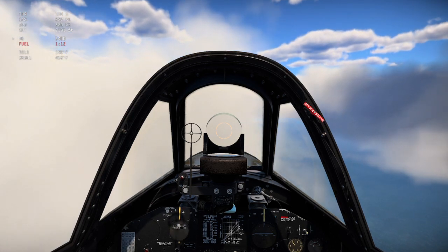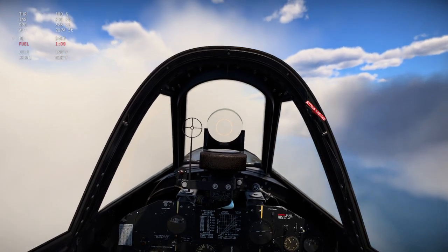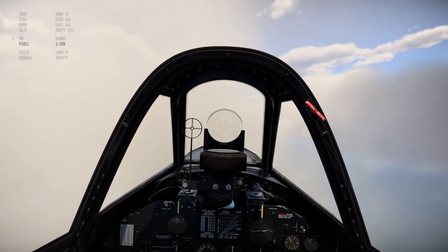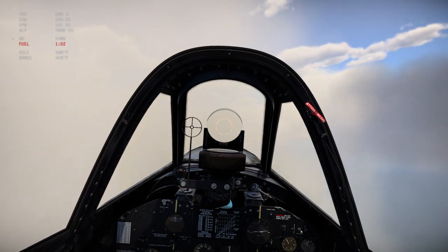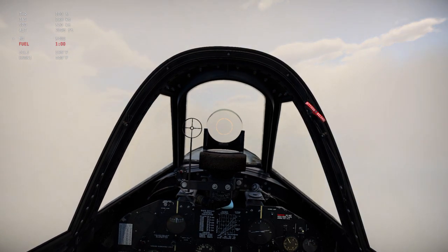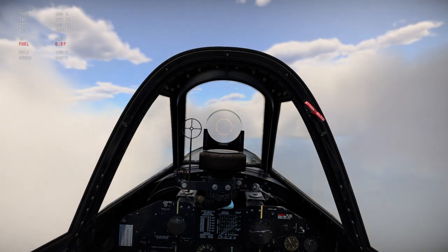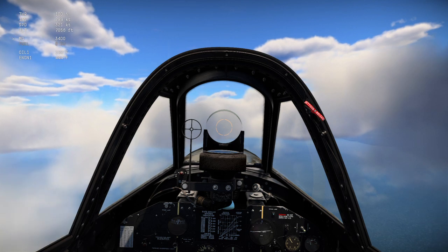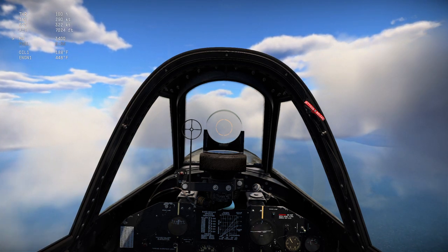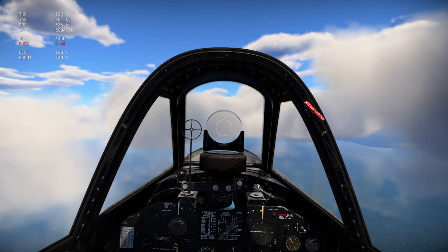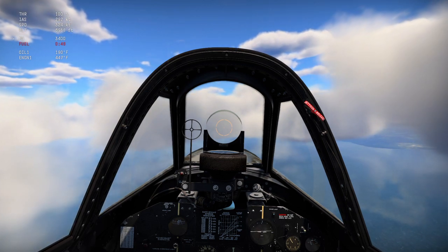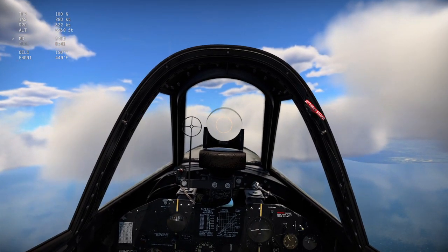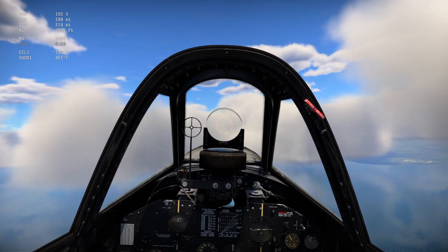Each engine is different. So just gauge if you start to lose power and you have more than one supercharger gear, turn your supercharger gear up if you're at higher altitude to get your power back. Every gear is going to be in 8 to 9,000 foot increments in altitude, or about 2,500 meter increments. So give or take. Each engine is different though, so you've got to gauge it yourself. But that's roughly about where it is.